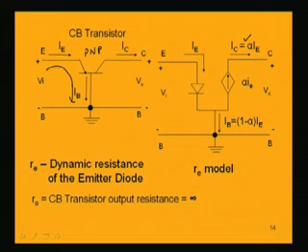This circuit of course has one more thing which is not shown here, which should be a resistance at the collector. This resistance is R0. Because of this fact that the resistance in the output characteristics, if we just recall the output resistance of a common base transistor, it is almost infinity. Because of the horizontal curves in the output characteristic, even if you go on increasing the collector to base voltage, the current IC does not change. It is almost having horizontal shape. It is like this type of IC we were getting across VCE.